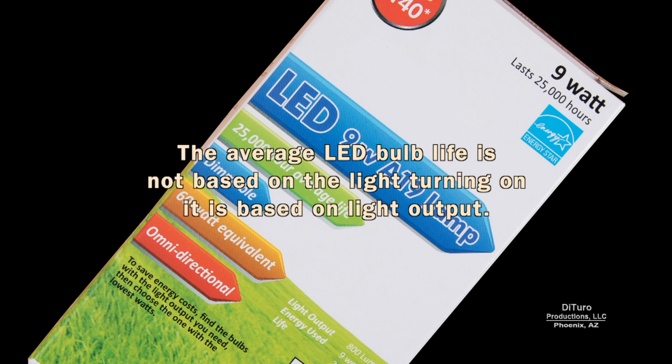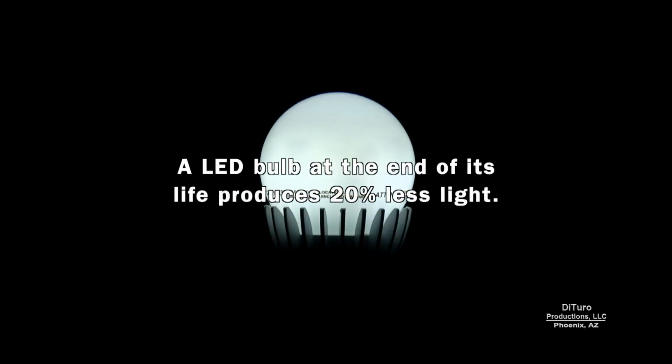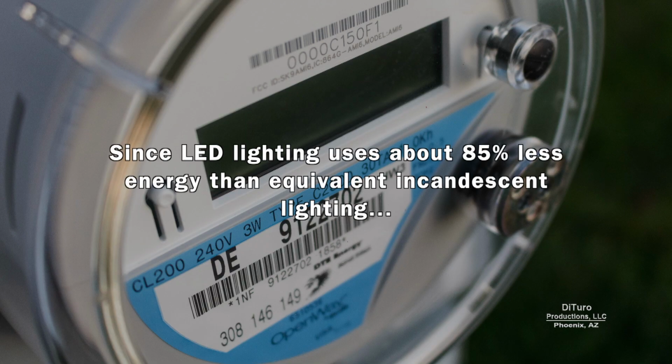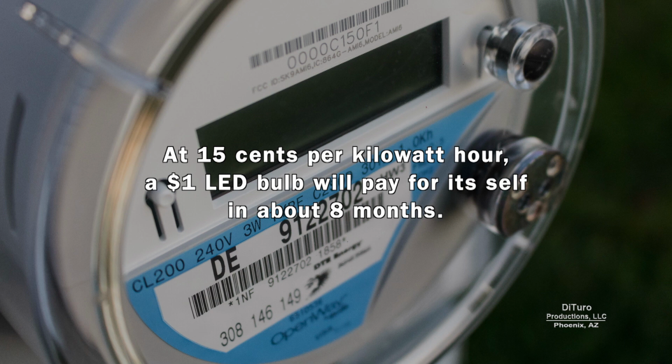The average LED bulb life is not based on the light turning on, it's based on light output. A LED bulb at the end of its life produces 20% less light. Like any product, some LED bulbs will meet or exceed their average life, and others will not. Since LED lighting uses about 85% less energy than equivalent incandescent lighting, at 15 cents per kilowatt hour, a LED bulb will pay for itself in about 8 months.